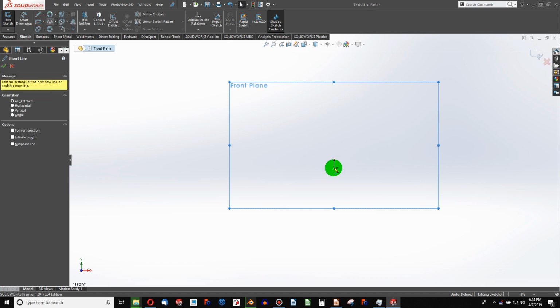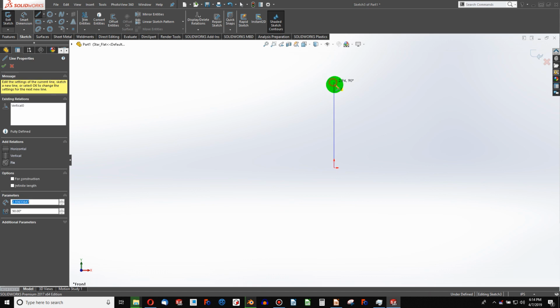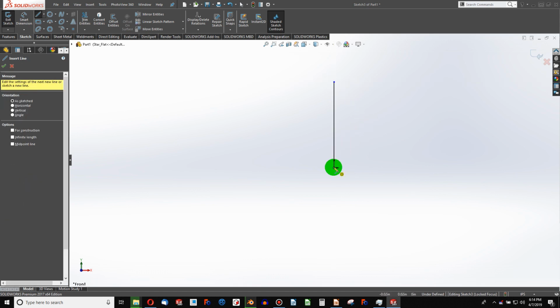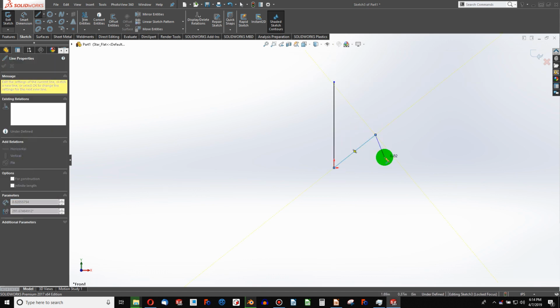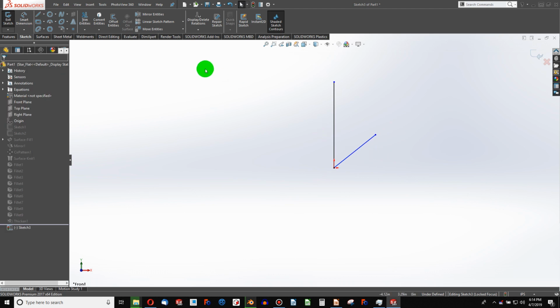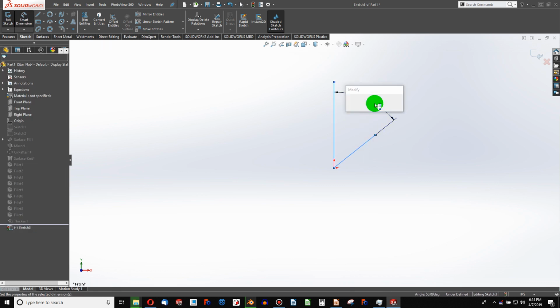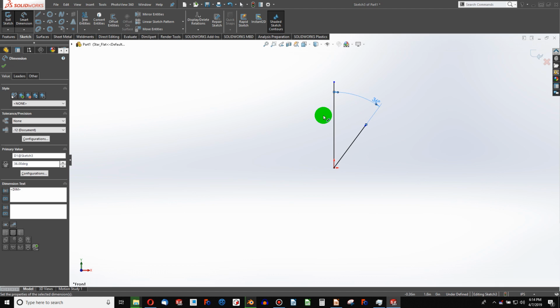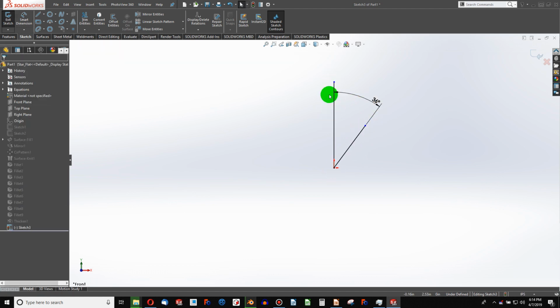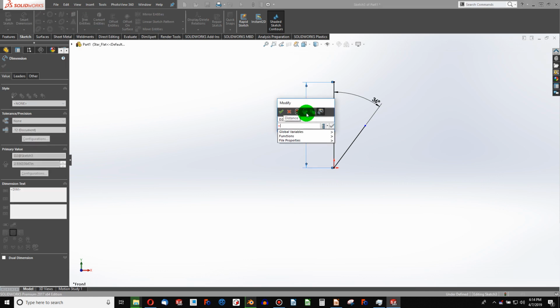This time I can just simply choose a straight up line and another line. And I can make these 36 degrees as normal. And now I know what length I need these when they're flat because I've got them in equation global variables. So I'll set a dimension equal to long length.